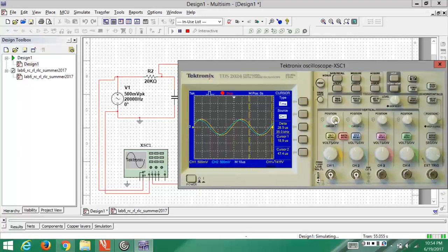And I place it on, yeah. If you look at the cursor now, it is right on the waveform where it intersects the x-axis, and take the reading for that time. I just moved cursor 1, so on the blue oscilloscope screen, I can see on the menu it says cursor 1 is 21.9 microsecond. So keep that reading somewhere written down. I had 21.9 for the yellow waveform in channel 1.